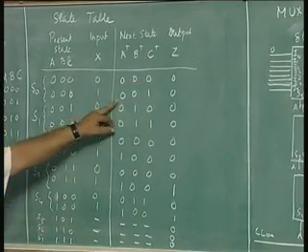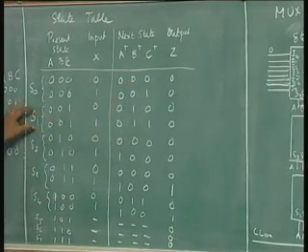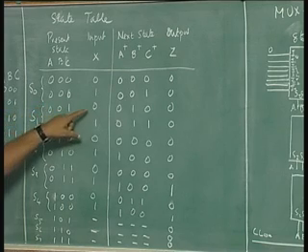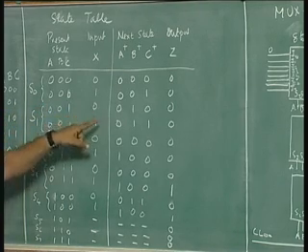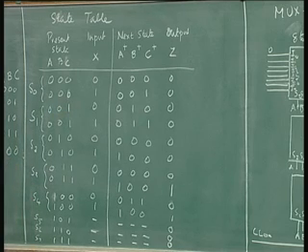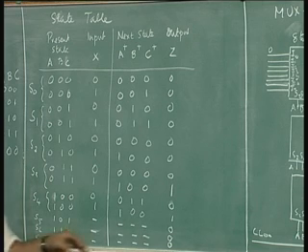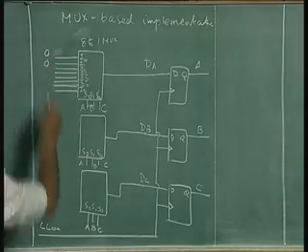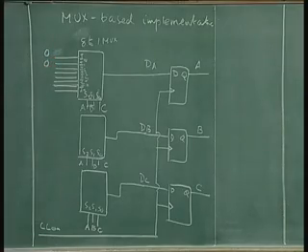So, the present state is 0 0 1, then S1 is S1 state, again irrespective of the value of X, the next state is a 0. Next state is a 0 irrespective of the value of X if the present state of the flip flops are A 0 0 1. So, again put a 0 here. Now, you know how to do this, it is a simple game we are playing, that is all.